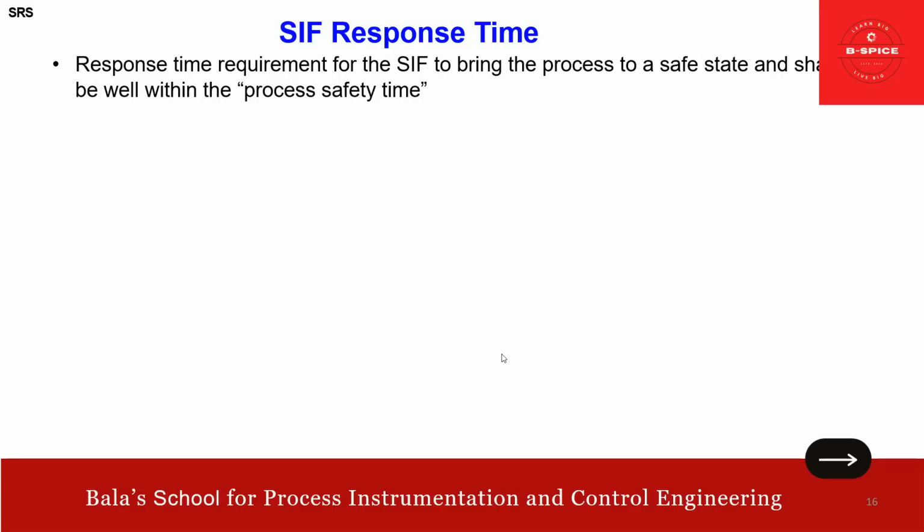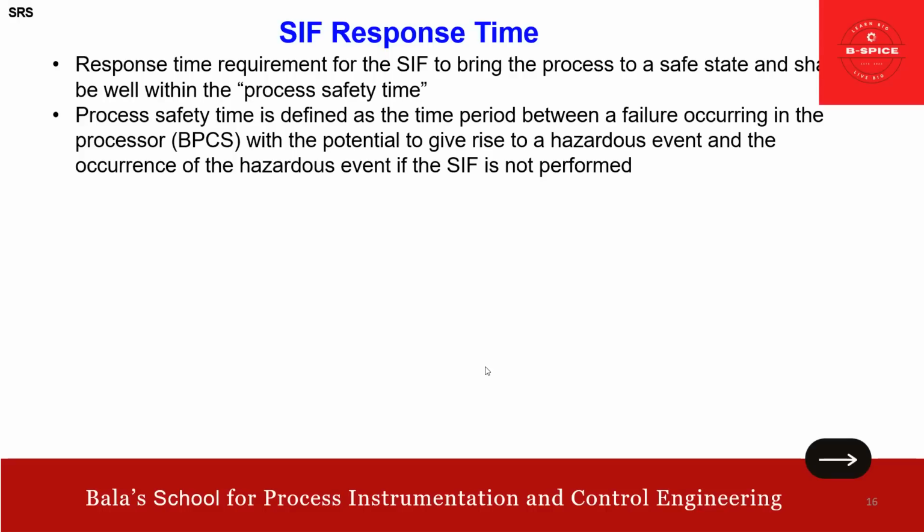Now, after this proof test, SIF response time. This is also another very important aspect, friends. See, basically the response time requirement for the SIF is to bring the process to a safe state, and shall be within the process safety time. That is very important. Take note, friends, the response time of the SIF to bring the process to a safe state shall be well within the process safety time. Of course, we need to check with our process colleagues on the process safety time.